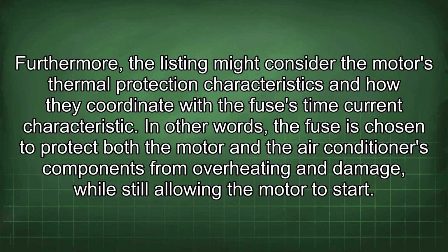Furthermore, the listing might consider the motor's thermal protection characteristics and how they coordinate with the fuse's time current characteristic. In other words, the fuse is chosen to protect both the motor and the air conditioner's components from overheating and damage, while still allowing the motor to start.